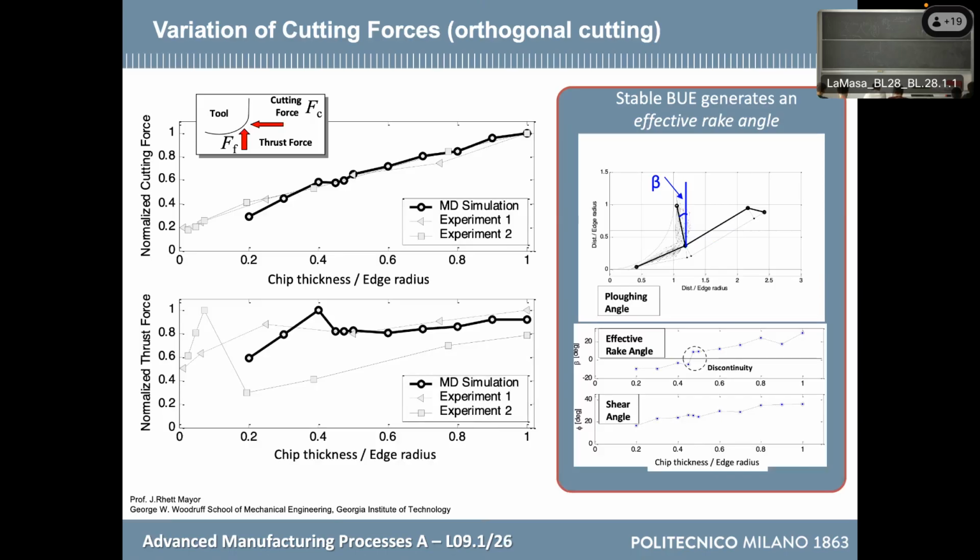And I can add also something more now, because in the top graph, you see the cutting force. The cutting force is, as I said, along the same direction of the cutting speed, which means that the material is flowing this way. And so this is the force. But now let's take a look also at the feed force. FF is the feed force, the perpendicular one.